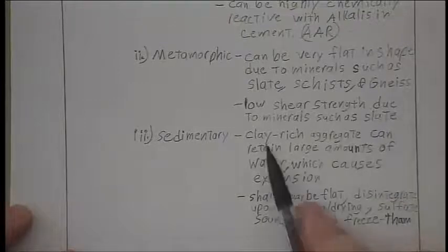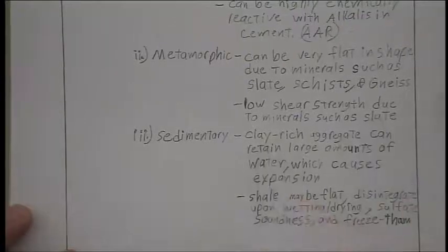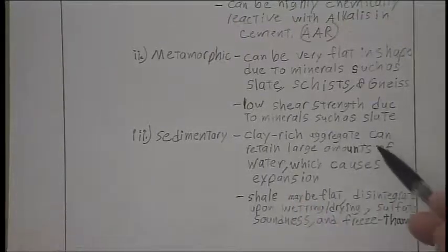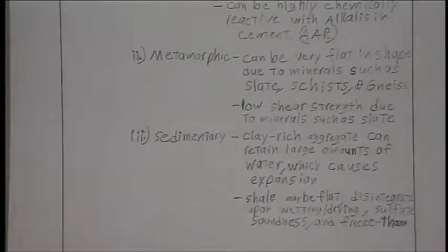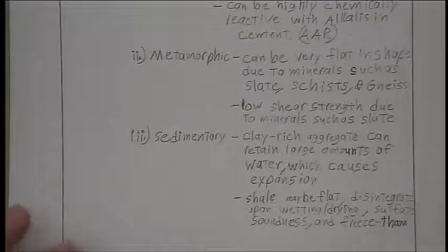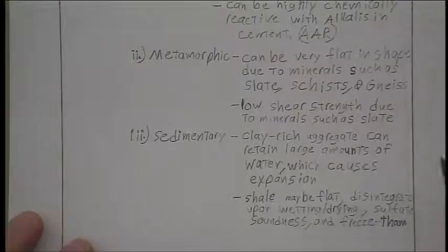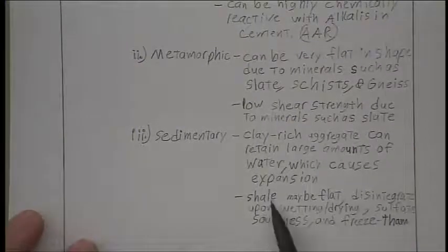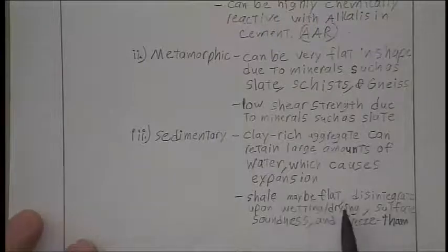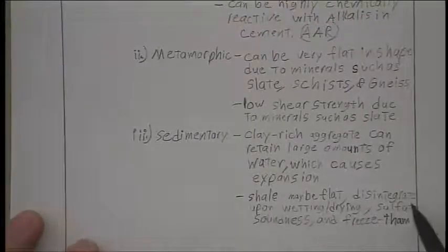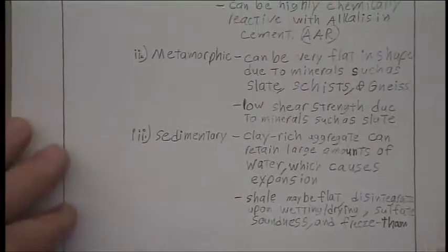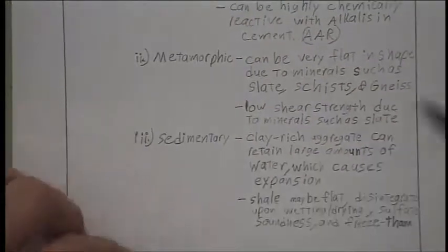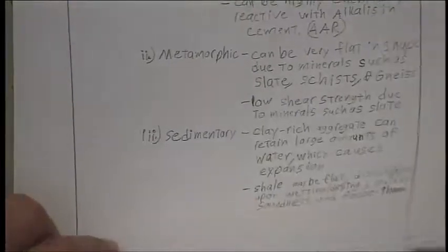Sedimentary may be a little more rich in clay, which retains a lot of water and will cause your material to expand a lot more. And then the shell can also be flat. There's a lot of shell, may be flat, disintegrate upon wetting, and sulfate soundness and freeze-thaw may be a lot of issues. So it's really important to understand what your chemical makeup is.